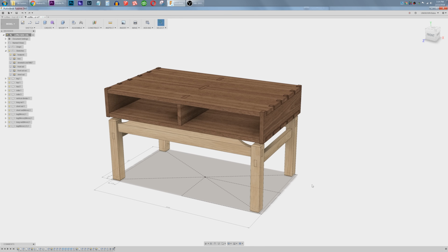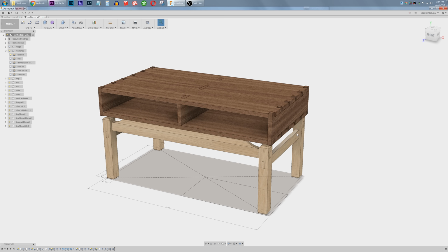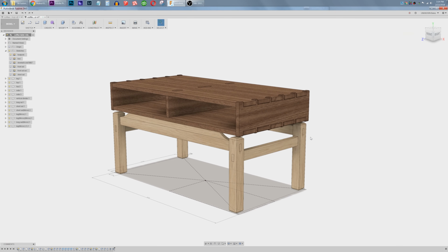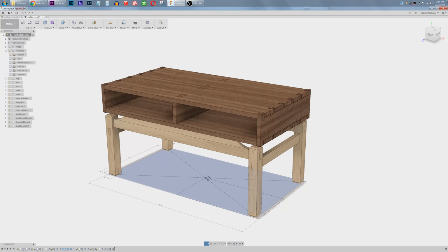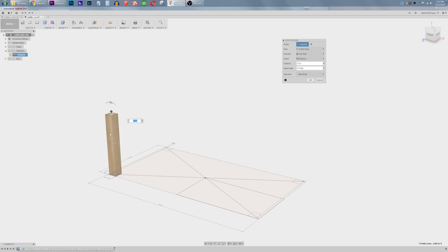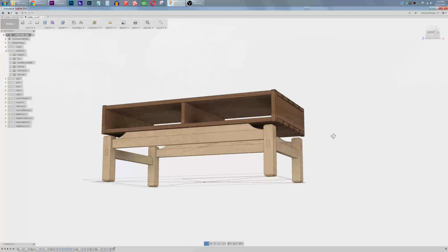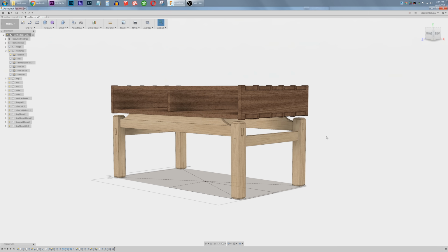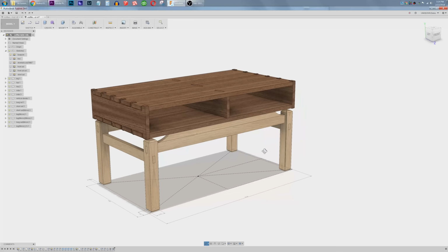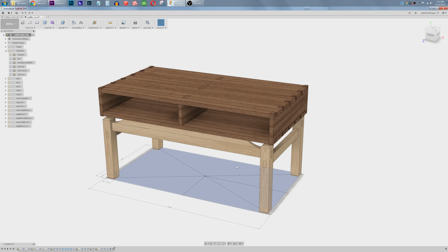When it's all said and done, you can go ahead and make updates on the fly, and everything else updates accordingly. So anyway, I thought that was very important of me to include that. And let's change this down to 9. And there we go. Everything updates accordingly. I thought it was important for me to show that because I did mention it a couple times in the video. Again, I want to drill it into your heads. Always make all of your sketches fully defined before you move on to the next sketch.